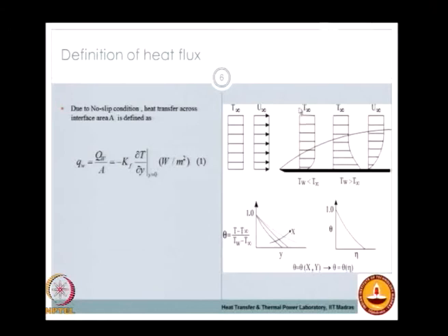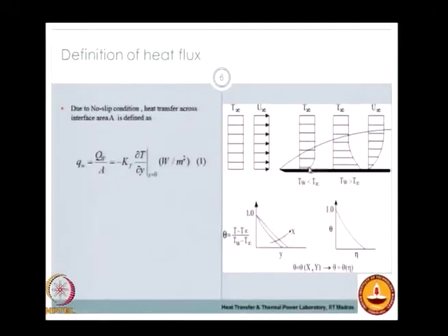This boundary layer is attributed to the no slip boundary condition at the wall, where the fluid has to take the velocity of the solid, which is stationary, and therefore the fluid has to be at rest. Essentially the lower layers of the fluid have lower momentum compared to the higher layers of the fluid, and this gives rise to the concept of the boundary layer.